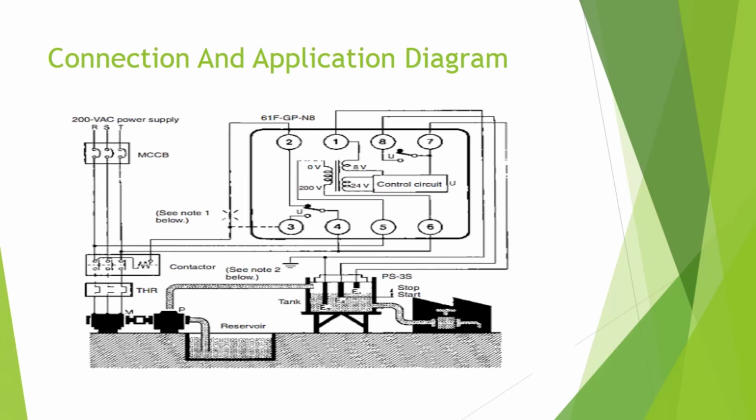First of all, its input source power I discussed in the past slide. Pins 5 and 6 are the 220 volt AC input source of this coil. You can see the mark here. Another point, pin number 4 is the common pin for the switching.